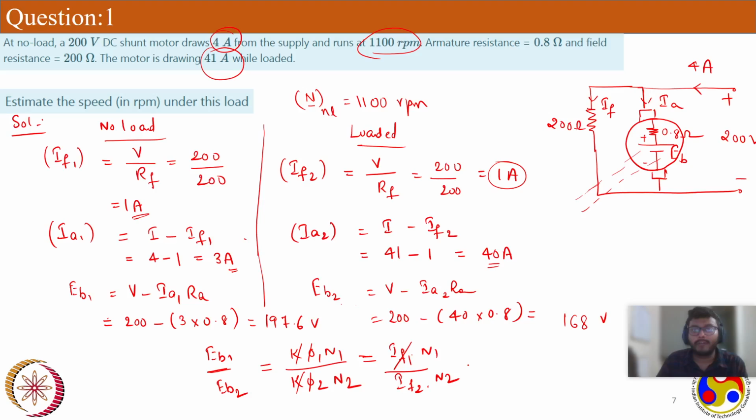P rotational is equal to VA IA. And the most important thing you have to keep in mind, it is at no load condition, because the losses supplied at no load are only rotational losses, as I have not connected any load to the shaft. So I have to specify here the armature current at this condition is the no load current. Now you subtract IA square RA at no load to get the rotational losses.